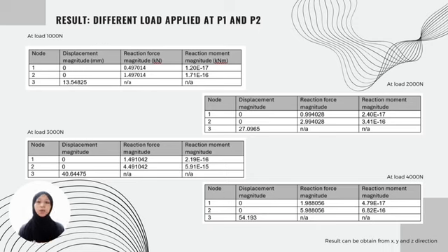For reaction force, node 1 is 0.497 kN and node 2 is higher at 1.497 kN, where the beam is experiencing major shear stress. Node 2 is where the beam is overhanging, so that's the reason why the shear stress is increased at that node. That is the moment. Node 2 and node 3 have very small reaction moments, but it still indicates the beam's tendency to rotate under the applied load.